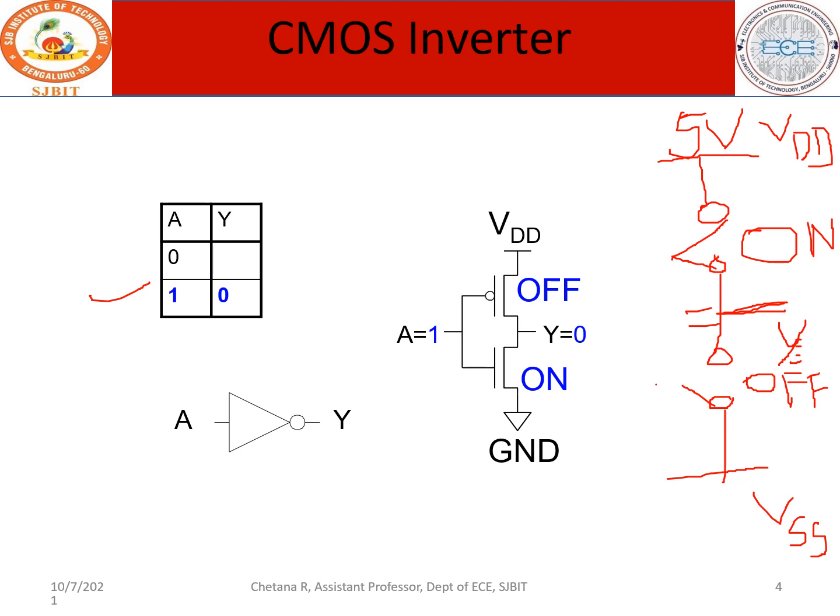It encounters a short, and the 5 volts will flow here. Always, that is how the strategy of every potential is. It has to reach the ground. So it tries to reach here. It comes here, it tries to reach here. It encounters an open circuit. So there is no path for 5 volts to go to the ground. And at that moment, when you check the voltage here, this will be 5 volts itself. So the voltage here is 5 volts. When we talk in terms of logic, it is nothing but 1.